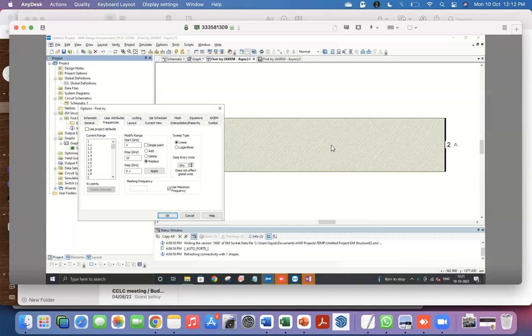Okay. For the EM structure, you might just solve it at 10 points or 11 points at 100 megahertz spacing. But then you want to use that in a different circuit which has maybe some inductors and capacitors. Maybe you're making a resonator which has a much sharper resonance, and you want to be able to look at that in a much finer grid.